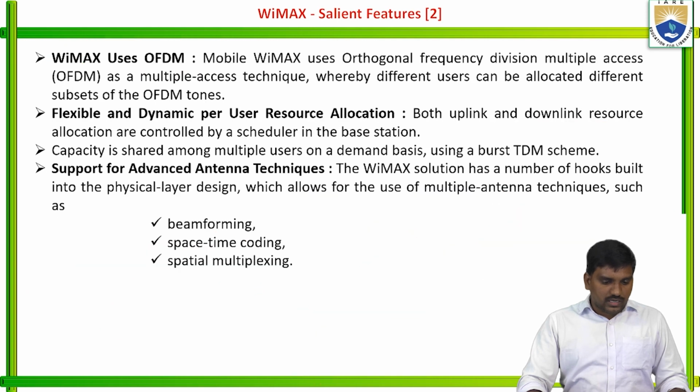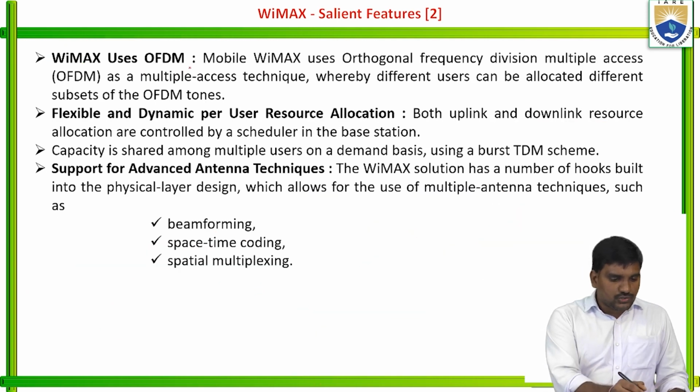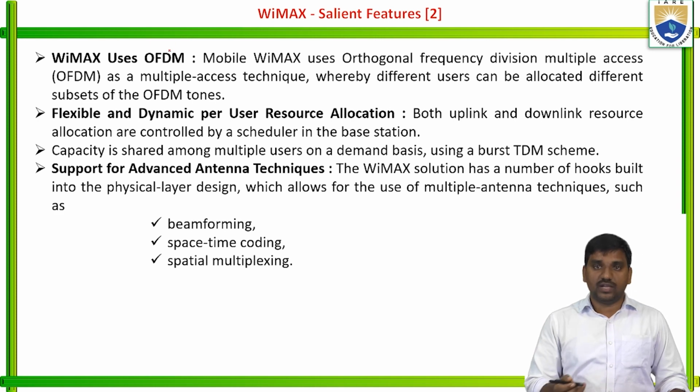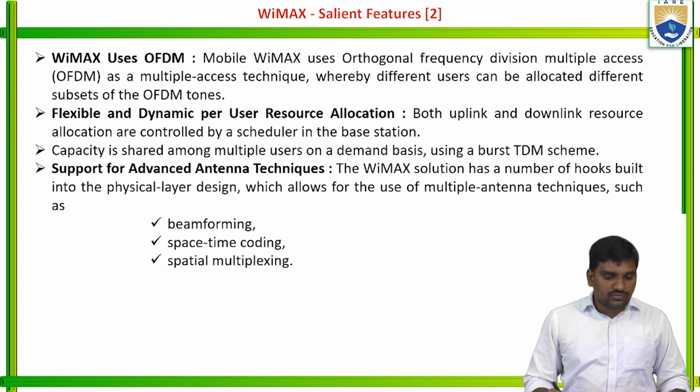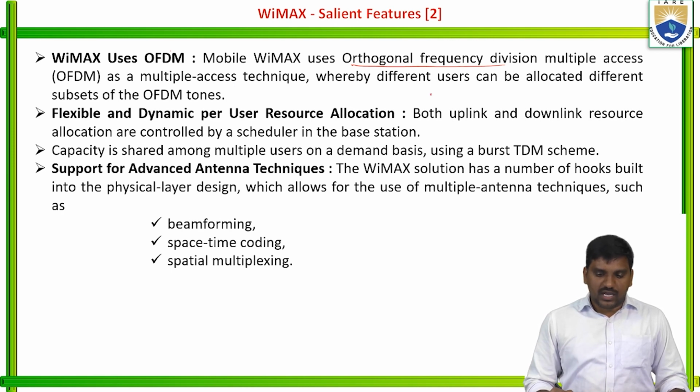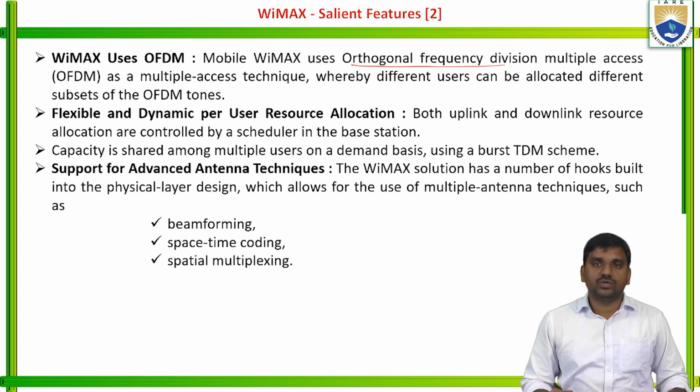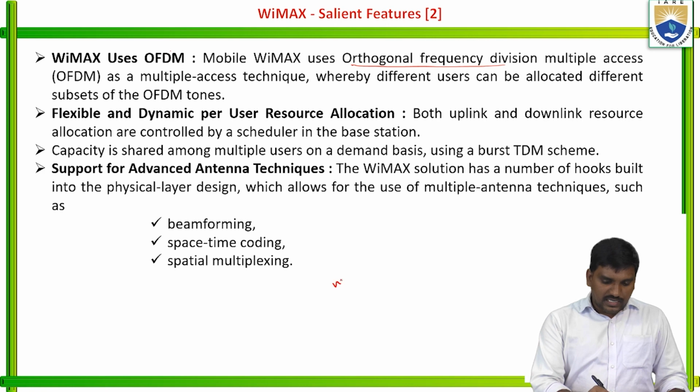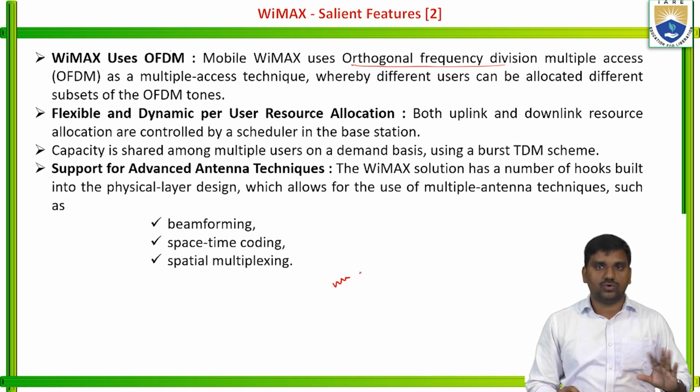Okay, so next remaining feature of WiMAX is that WiMAX uses OFDMA also. We already know orthogonal frequency division multiplexing. OFDMA is a multiple access technique whereby different users can be allotted different subsets of OFDM tones. So multiplexing techniques are different; multiple access is totally different.